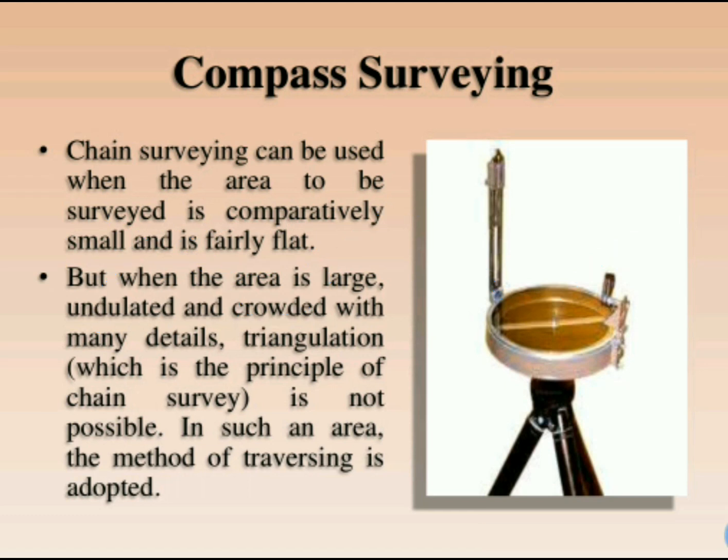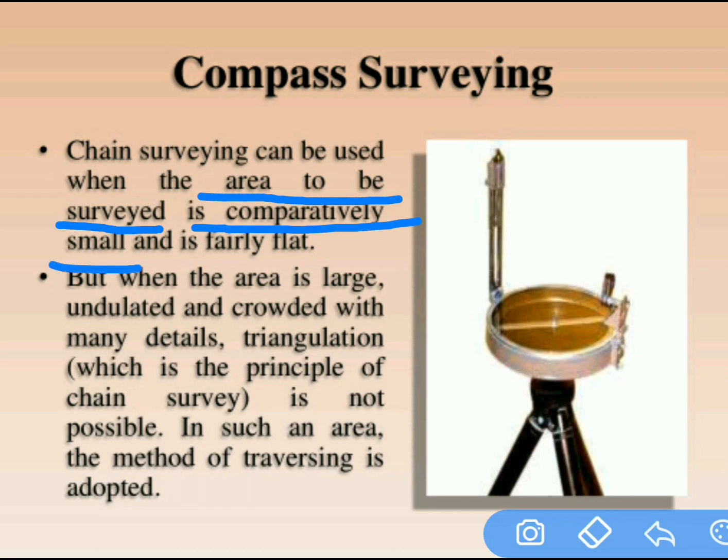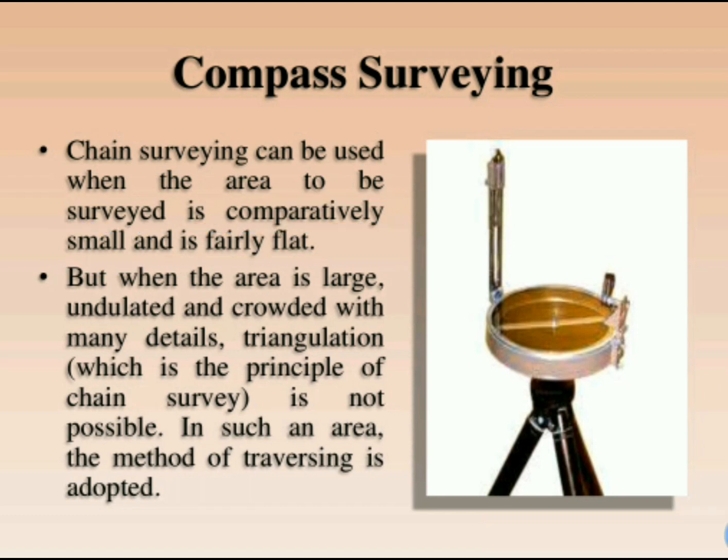Yes or no? Yes. So here, chain surveying can be used when the area to be surveyed is comparatively small and fairly flat, then only chain surveying is suitable.